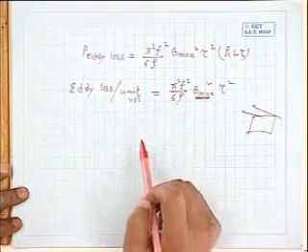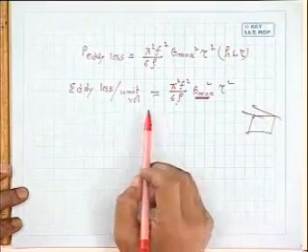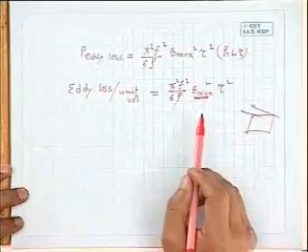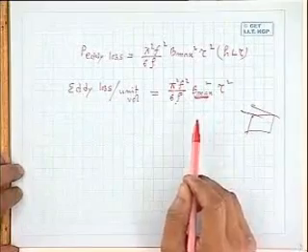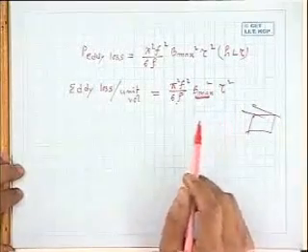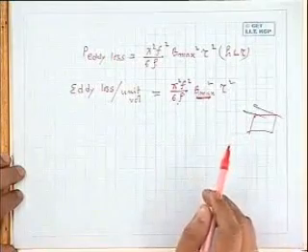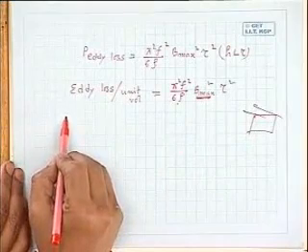Obviously, one should see this eddy current loss should be as small as possible. You should try to use higher resistivity material. So this you just remember. This is the expression for the eddy current loss per unit volume, and it is directly proportional to the square of the frequency and the maximum value of the flux density squared.